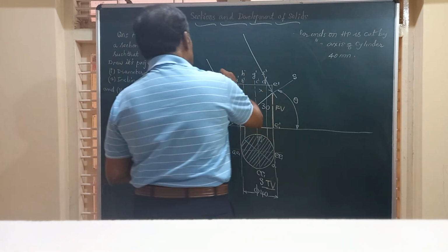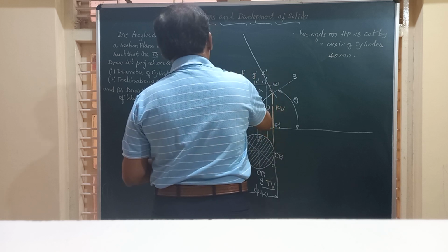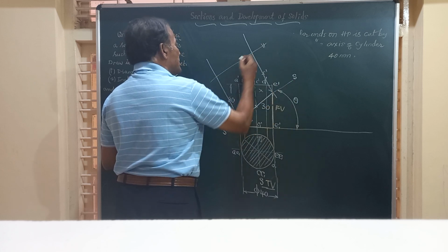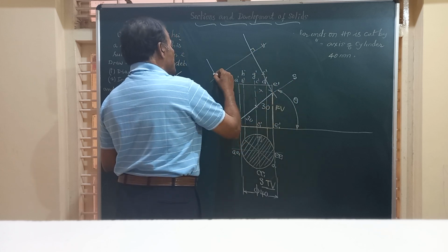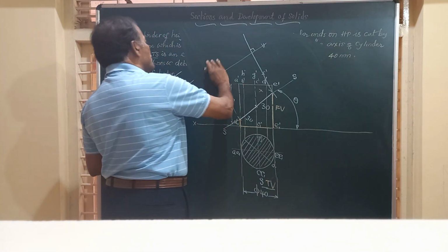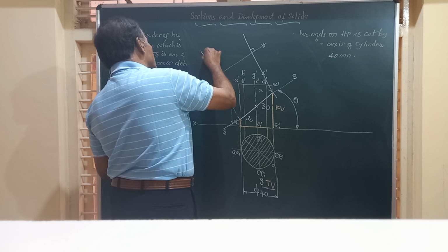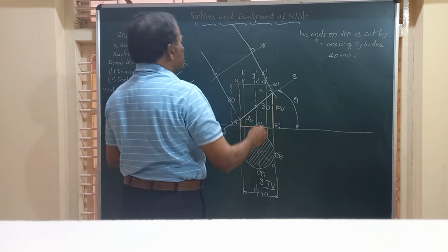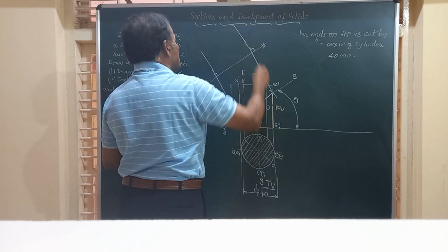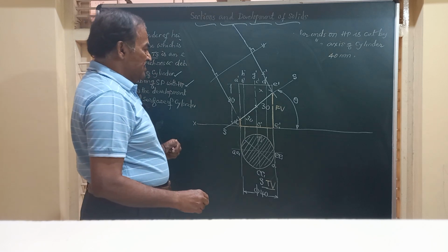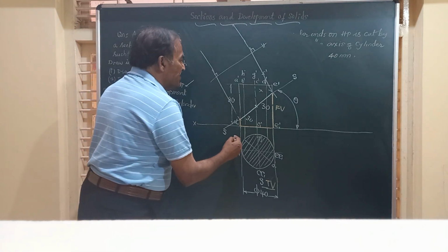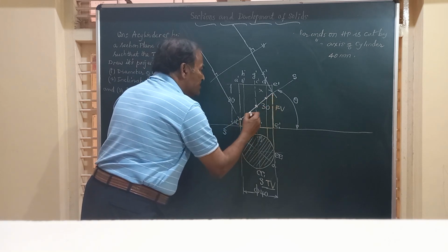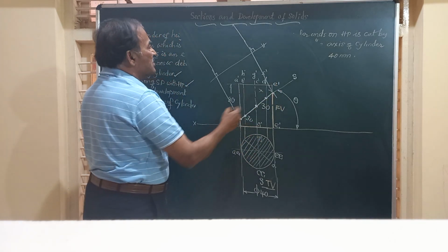Now friends, I am going to draw a line parallel to SS. So very obviously, this is parallel to SS, but it is perpendicular to this line. So friends, here I should get what is known as the true shape of the section, which is going to be an ellipse. And only based on that, we were able to find out the diameter of the cylinder. Friends, just see here, all the 8 generators, AA, BB, CC, DD, etc., are all cut here, friends.